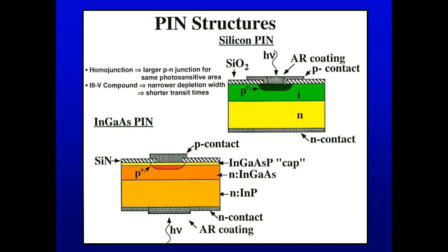Okay, next we come to the indium gallium arsenide PIN. Here the combination is of group 3 and 5 components, therefore you have a narrow depletion with a shorter transit time. So your peak power is high in this indium gallium arsenide PIN diode. You have an incident photon, we have the PIN, and the intrinsic region is made up of a different combination of the indium gallium arsenide and phosphide region. According to that, we obtain the optical power input and derive an electrical charge output.